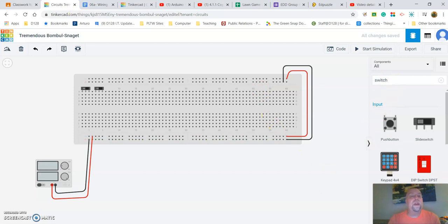Next thing I need to look at is my circuit, which is going to be A bar B plus AB, right? So what chips or gates am I going to use? I'm going to use an inverter, an AND gate, and an OR gate. A bar means I need an inverter from A. Then A bar B means I need an AND gate, and AB needs an AND gate. And then the plus means those two AND gates go into an OR gate, okay?